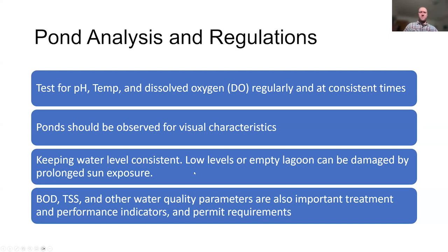Just real quick, lagoons and constructed wetlands are going to be two different types of processes, like you said. A wetland is going to be more of a polishing process, while a lagoon is going to act more as your primary treatment mechanism. And a lot of that vegetation interferes with the lagoon process, such as blocking sunlight. Most of the time, you don't want big vegetation, but you want a short grass on your banks to prevent erosion. So that's typically how those two concepts are balanced.